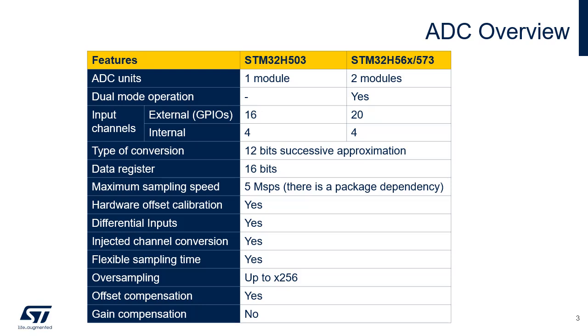The maximum oversampling ratio is 256. ADC's conversions are organized in two groups, regular and injected group. Raw samples acquired by ADC may be processed by the oversampler and offset compensation units before being provided to the software. For power-sensitive applications, the ADC offers several low-power features.